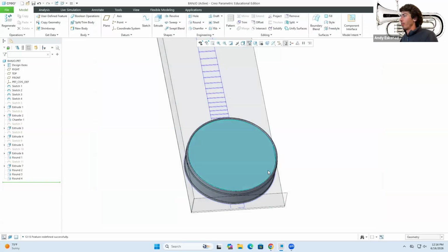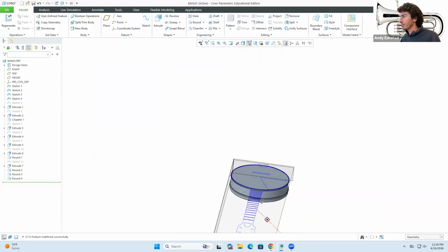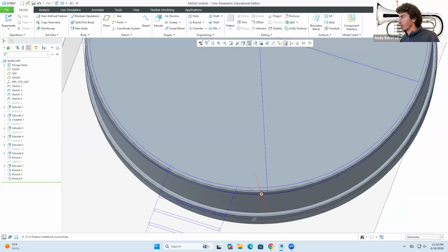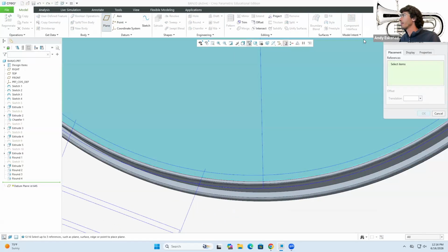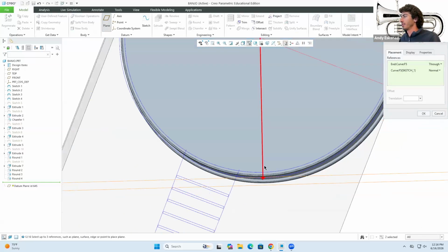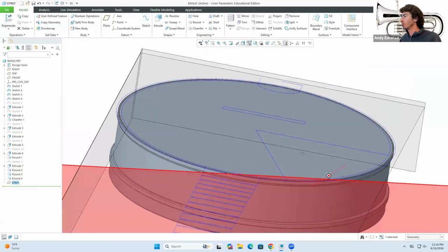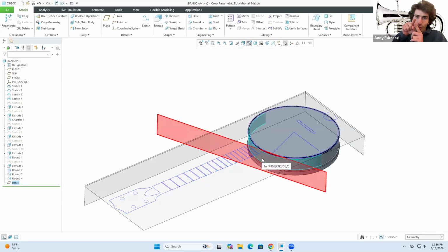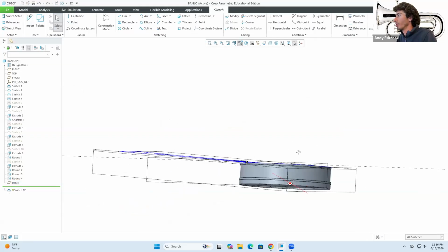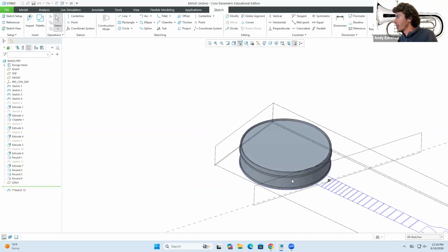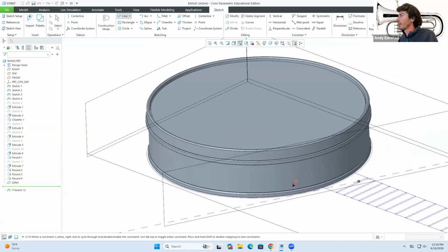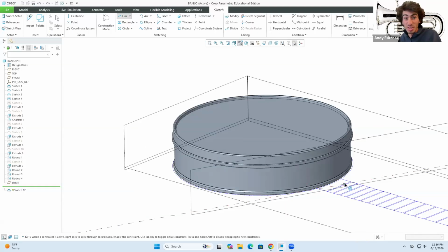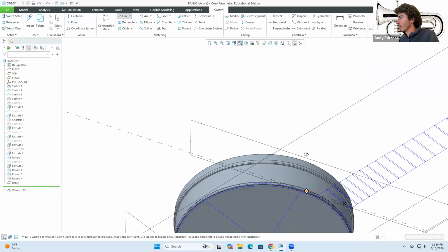So my approach for doing this will be as follows. I'm gonna come over here, and since we conveniently have that line drawn out, I go here to plane, and I will click on that line like this, and now we have an angled plane right there. And you will see that afterwards, I'm gonna make a nice pattern of all of these things. So go here to sketch. Very good, so it automatically recognizes that I'm here. Excellent. So now what I can do is, let's see where is my origin. So it puts my origin there, which is not necessarily what I wanted.